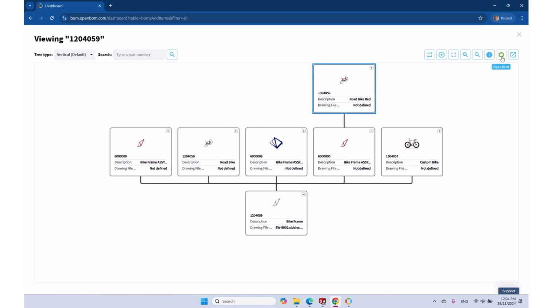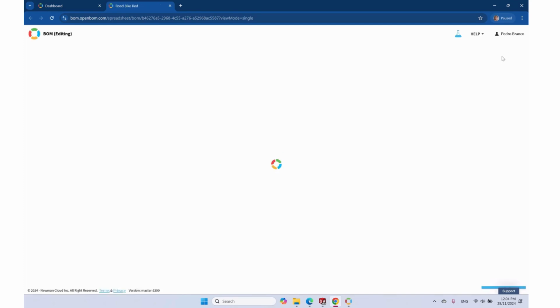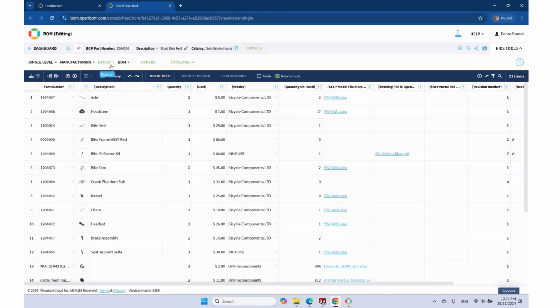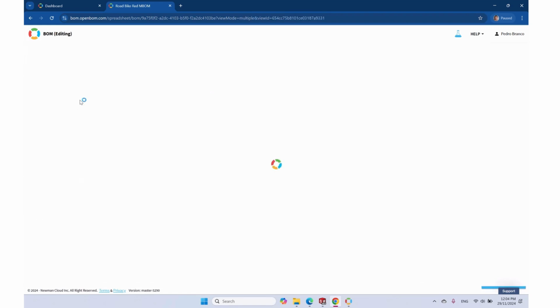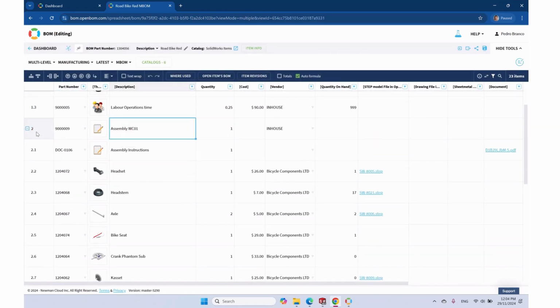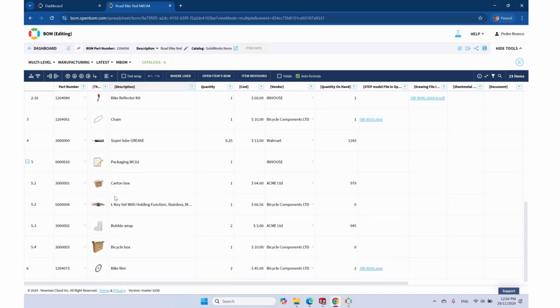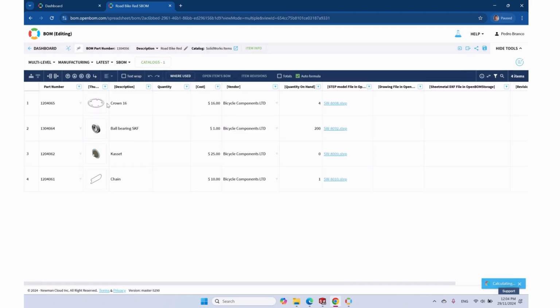quickly and easily. A digital bill of material also goes through different life cycles and stages of the product, like design, engineering, manufacturing, and service. So you can see how those structures are connected. So this is an engineering bill of material structure you see here, but you can quickly switch to a manufacturing bill of material structure that has a sequence of operations. It has different assemblies and sub-assemblies, more focus on work centers. So we have a work center for assembly and a work center for packaging. You can also connect it with the service bill of material where you can see spare parts and you can help your sales team to work more efficiently on a complete digital bill of material.